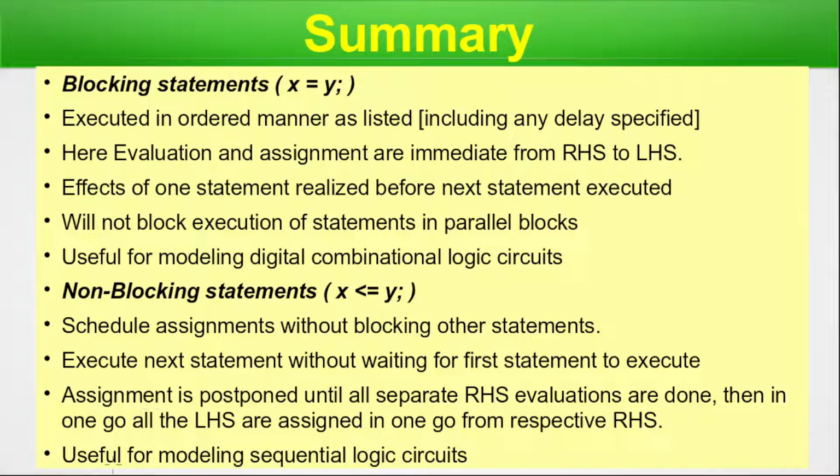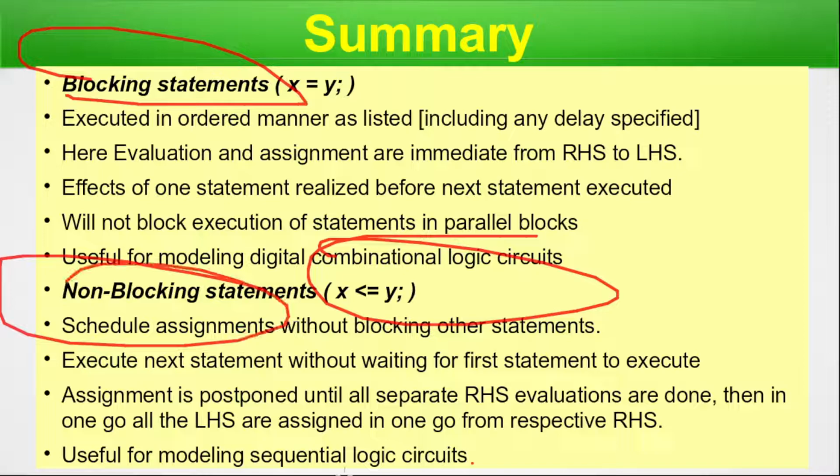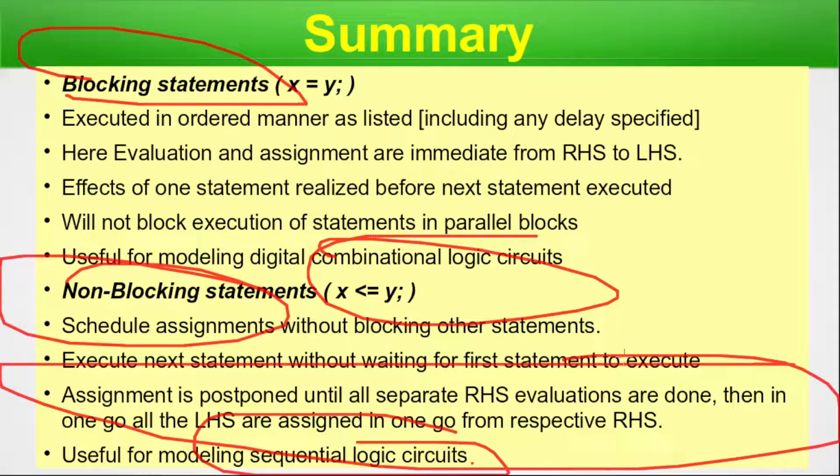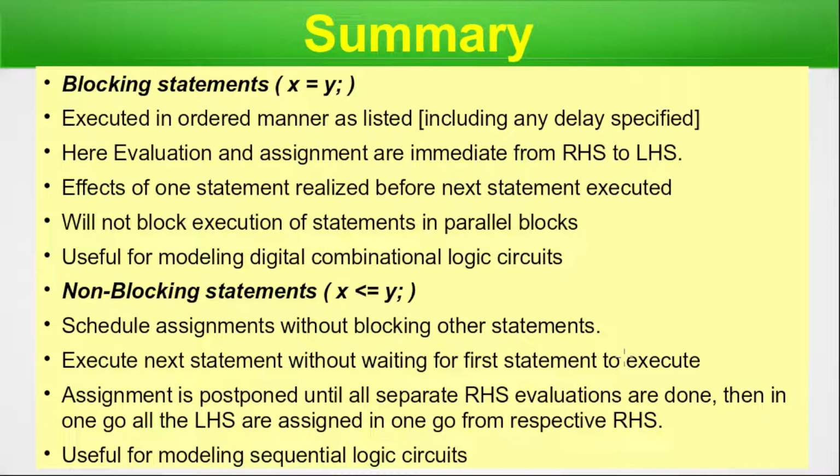So this is very useful for modeling sequential logic circuits. We are done with the summary here, and we have the striking differences. The blocking is for combinational circuits, the non-blocking is for sequential circuits, and how this happens we have also explained throughout the episode, and we have summarized in the summary slide. So let's move on to our next section where we will do the code simulation.